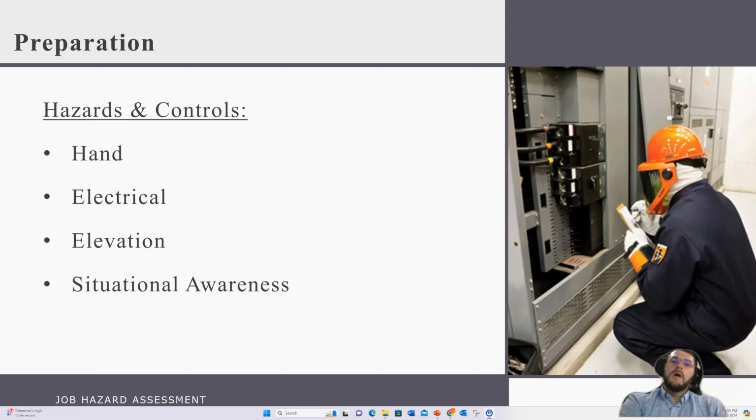You're also going to be performing work from the aerial work platform during these preparations. So be aware of elevated work protocol. Make sure you're wearing proper fall protection, harnesses. We also have a double lanyard or 100% tie-off rule here, so make sure we wear double lanyards at all times. Anchor points, have one tie-off per anchor on our aerial work platform. Make sure we follow those proper standards too.